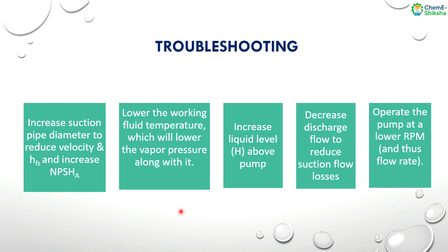Now the point of troubleshooting. That means how to troubleshoot, how to ensure there is no cavitation. We know that to ensure there is no cavitation, NPSH available should be more than the NPSH required. So somehow we have to increase the NPSH available.